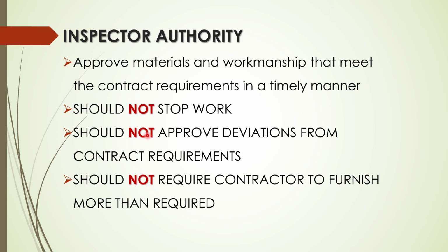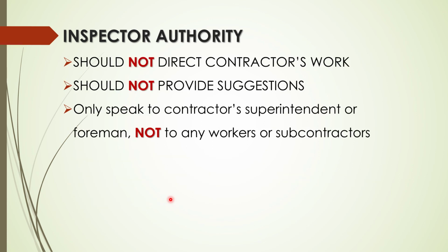Don't approve any deviations unless it came through the pipeline, through the superintendent, through the engineers, and you see documentation that this is okay. So you have to make sure you have the documentation. And don't have the contractor do more than what's required.